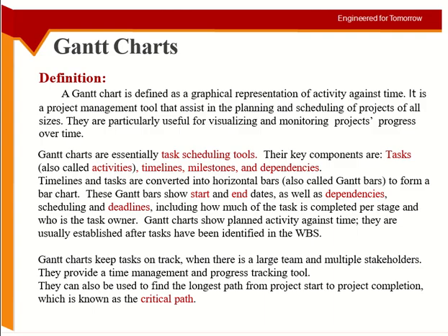So concreting is, let's say, 20% of the whole project. You can write additional information on the Gantt chart as well. If you are using software, the software does it for you. You define the total duration and the duration and total cost of each activity, and it gives you a percentage by itself. So when you finish one activity, you know how much of the project you have completed. They show planning of activity against time, and the activities will obviously come from the WBS.